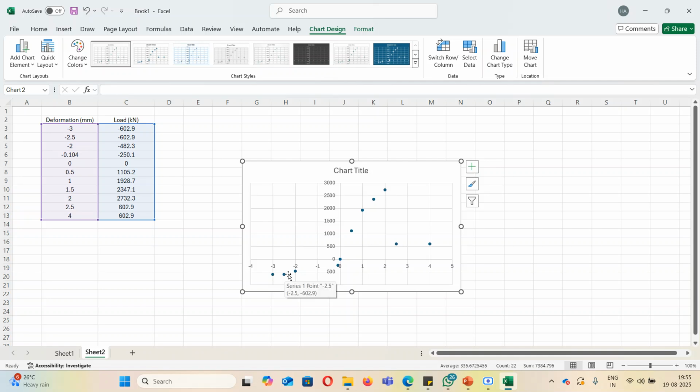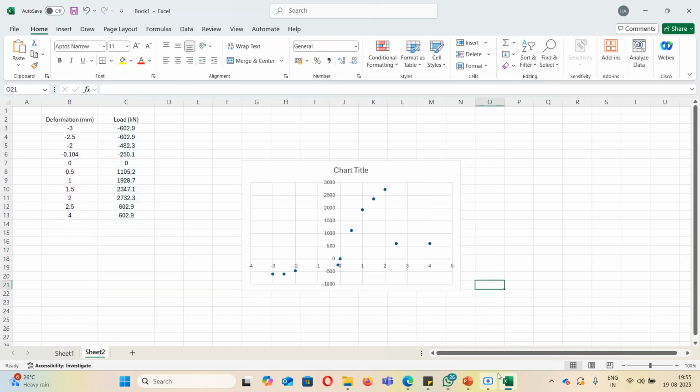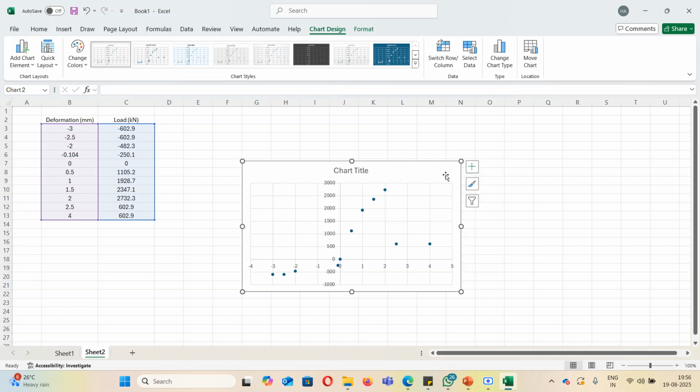This is linear. If I had plain concrete it would have dropped from here till 0, but now it has a linear increasing part till here, and then it is becoming constant. On the compression side it is showing a linear increase, then a parabolic increase, and then after peak strain it is showing a constant value which is taken by the steel, and the contribution of concrete has dropped to 0. Okay, so this is how we plot the stress versus strain profile, or load versus deformation profile, for a reinforced concrete system. Any doubt in this?